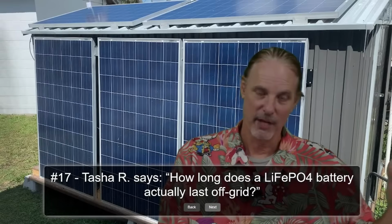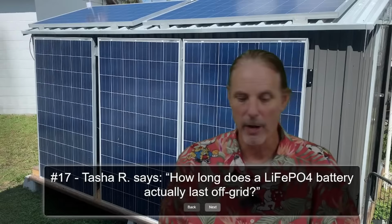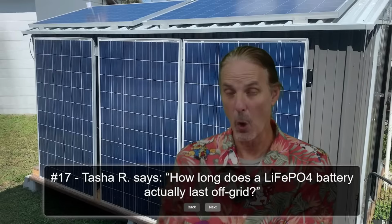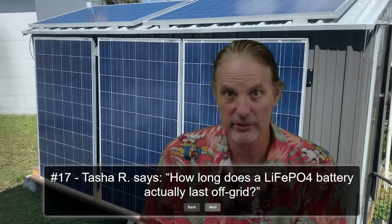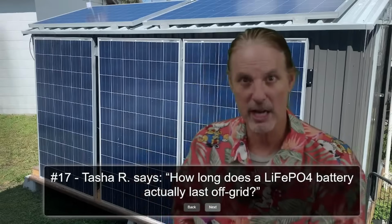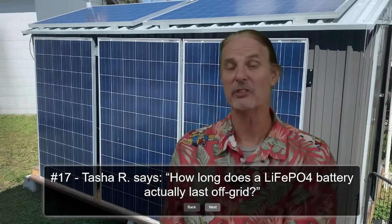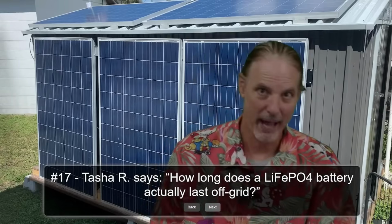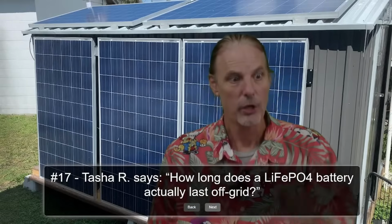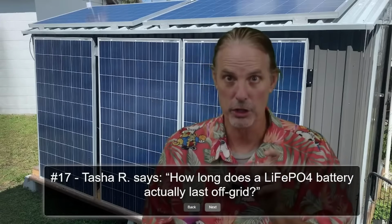In other words, if you are going to discharge your battery all the way down to 0 and you charge it all the way back up and it stops at 90% and only resets to 100% because it hit the high voltage, you recognize, or I hope you would recognize, that 10% of your battery is missing. And if 10% of your battery is missing and you call it 100%, then your battery will die at 10% and your state of charge will be wrong again. So actually, the life of the battery becomes the real question here.